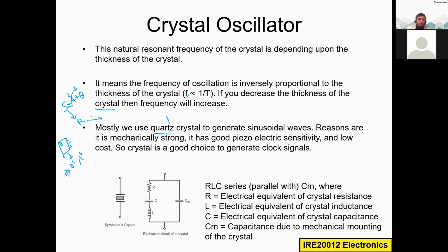Here we need to synchronize. We need to read the data A from register R1 and the data B from register R2, so we need some kind of synchronization. So we need clock signals. Whenever the clock signal rises from 0 to 1, the rising edge, I read the data from R1, and on the same rising edge, I read the data from R2.